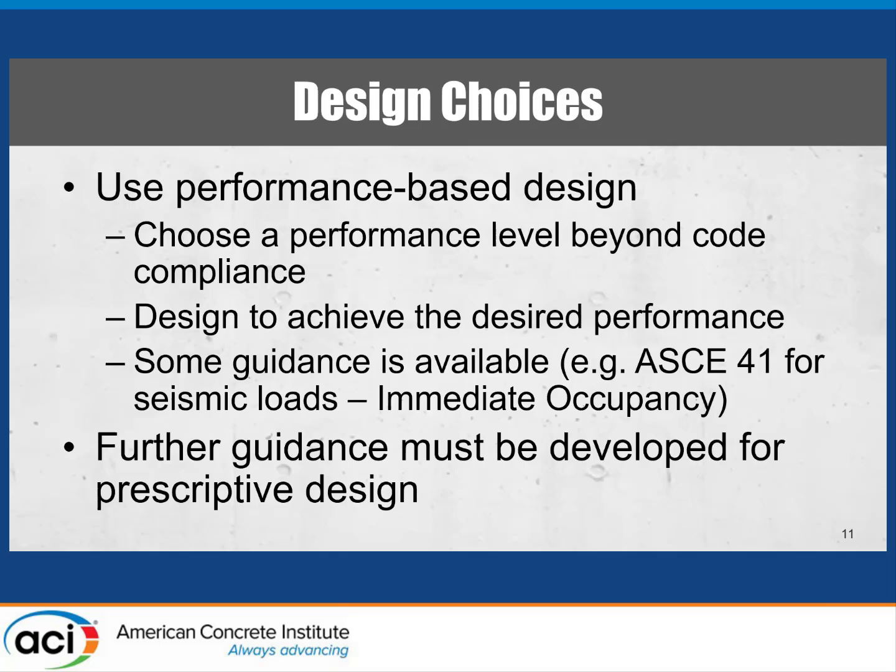There's been a lot of work that's gone into that. It's a very detailed guidance on how to achieve specific levels of performance beyond life safety. Immediate occupancy being the most widely used one for hospitals and other critical structures. But further guidance has to be developed, not only for performance-based design for loads other than seismic, but for prescriptive design, because realistically, the vast majority of buildings in the foreseeable future will still be designed using prescriptive design methods. They're not going to go to a full performance-based design with nonlinear analysis and peer review and the rest. So it's very important that we look at developing these guidelines for prescriptive design.